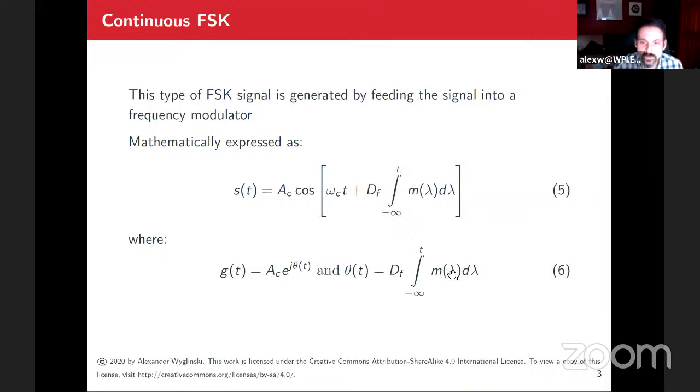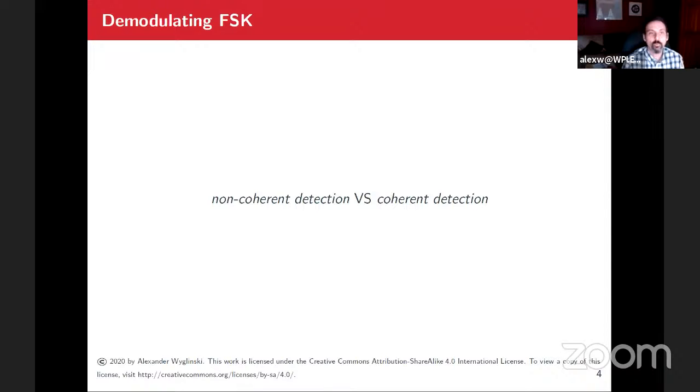So you would have this. First of all, you need to have some sort of translation of that message signal. Remember, it's binary values, right? So those binary values need to be translated into that m of t waveform, and then that m of t waveform is what allows you to transition to this phase value that ultimately goes into your s of t, right?